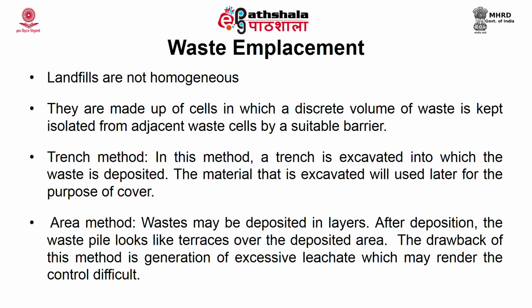In the area method, waste may be deposited in layers so that it forms a terrace arrangement. For example, the entire landfill will be layered with waste at one stretch. Once the entire landfill is full, then the second layer will be placed. It is not in portions or parts. So, this gives a terrace sort of arrangement.